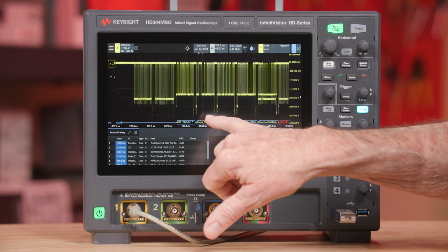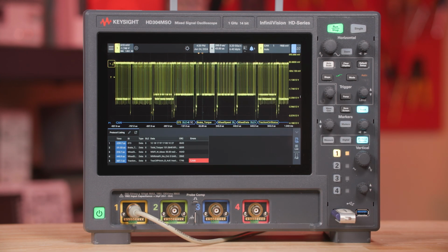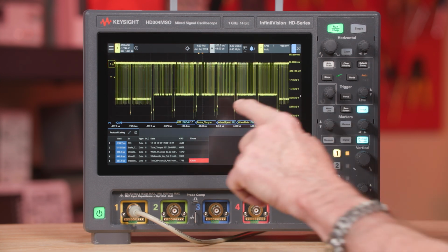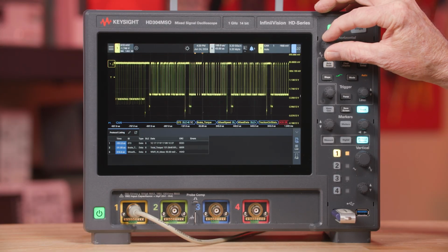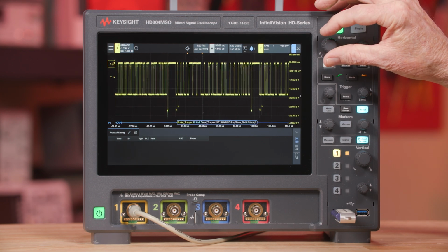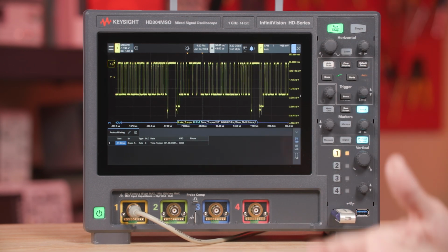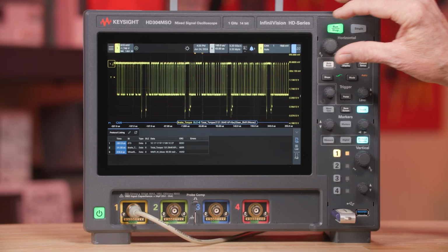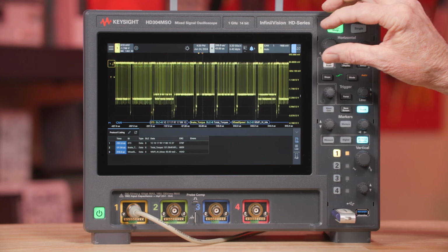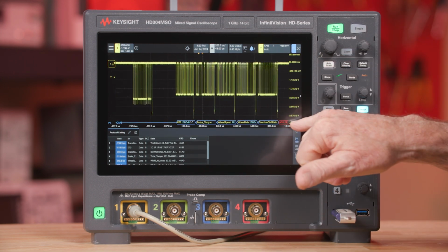The frame we were triggering on, 211, we're still triggering on that frame, but it has a name of brake torque, and we could set the scope up to trigger on message names as well. We could zoom in further and see the various signals within this frame, along with signal names, transfer functions, and units.